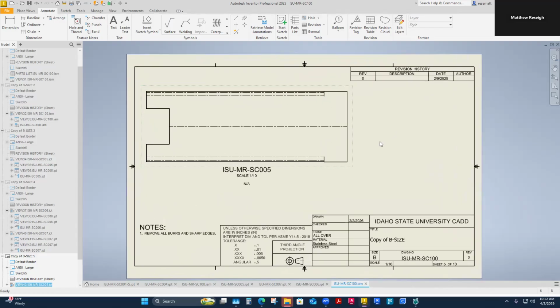Eventually, we'll come down and strip off the revision histories because my first revision zero will pretty much just have one revision block on the very first sheet. And then as revisions happen and they impact sheets, I start adding those revision blocks onto those specific sheets that they've been impacted. My first revision history will always be the master list of all the revisions, right?